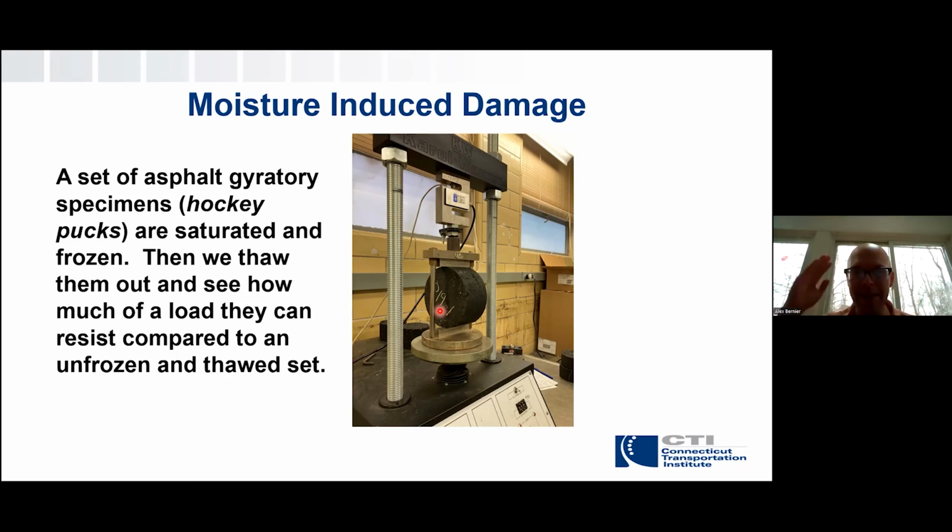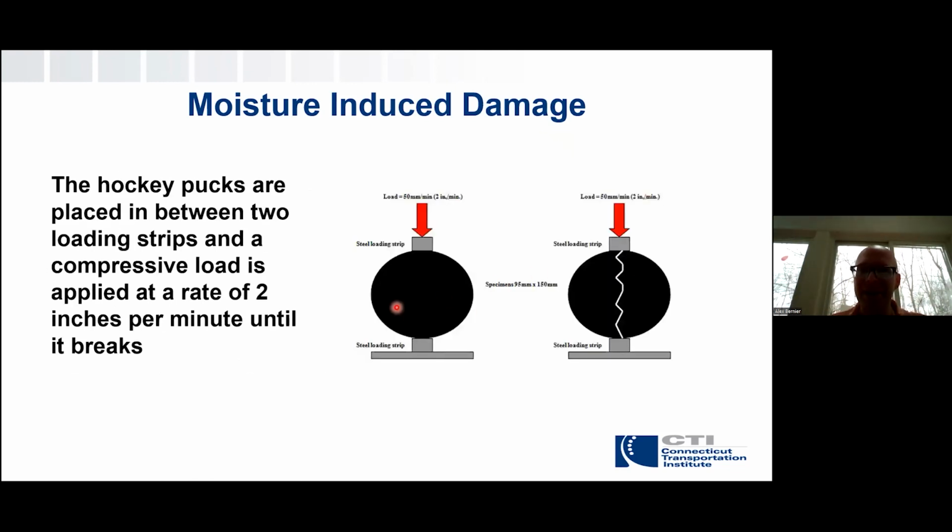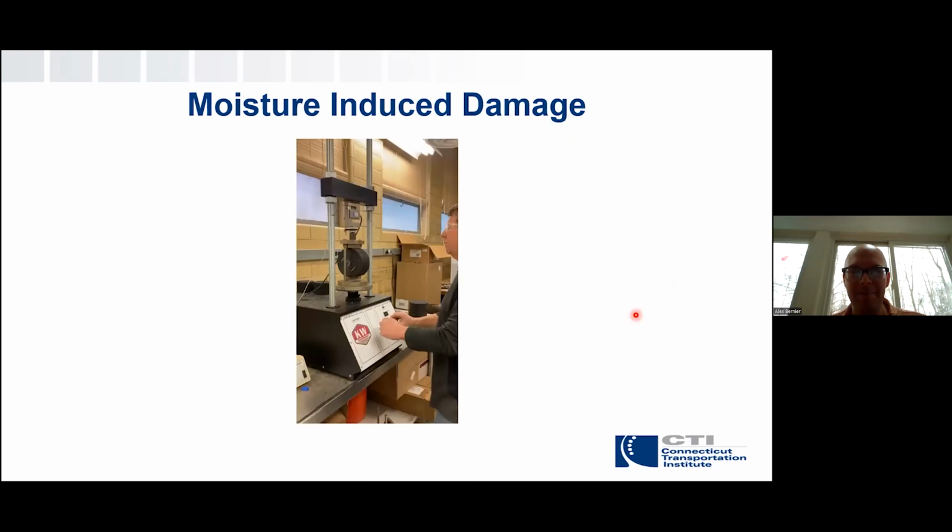If you go deeper into engineering, there's something called mechanics of materials where you would be able to analyze what's happening inside this specimen as you fracture it, but it's actually going to fail in a crack straight up this way because of tensile strain concentrations in the specimen. A little extra information for you there, but the key is we're going to test the control versus the damaged ones and see the difference.